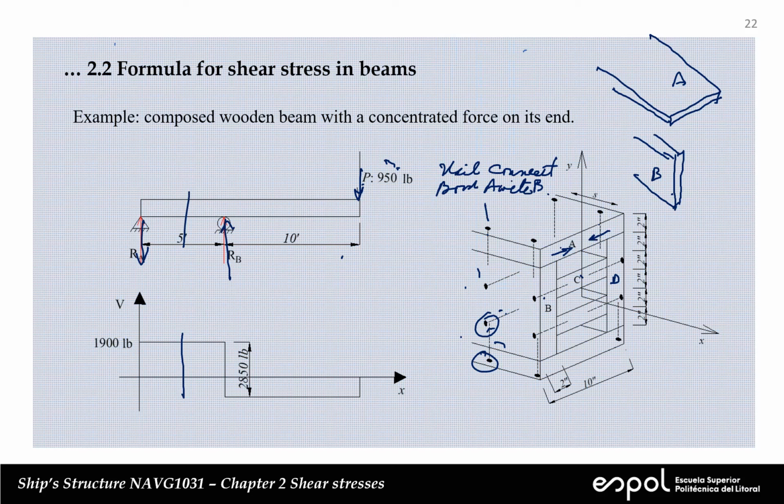But the problem is that we have to calculate the first moment, and the first moment is a continuous function. How can we change sign in going from the left side of the flange to the right-hand side of the flange? The only way is if the stress on the left-hand side decreases, and when we go through the symmetry axis, the value of the shear stress has to be 0. Then on the other side, we're going to have the stress, but with a different sign.